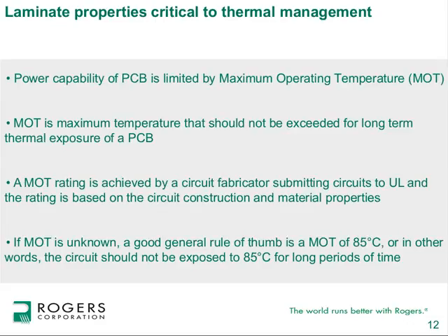When a fabricator makes a circuit, they generally make a circuit of multiple laminates and prepregs, and that goes through certain processes. They submit it to UL, and then UL does testing and comes back and tells them that circuit is rated to such and such temperature for MOT, and that's the maximum temperature that circuit can operate at. Any temperature at the MOT or less is fine for the circuit to operate at indefinitely without degradation to critical properties. Anything beyond the MOT temperature, then all bets are off. Bad things are going to happen sooner or later. So not violating the MOT is the big issue here.